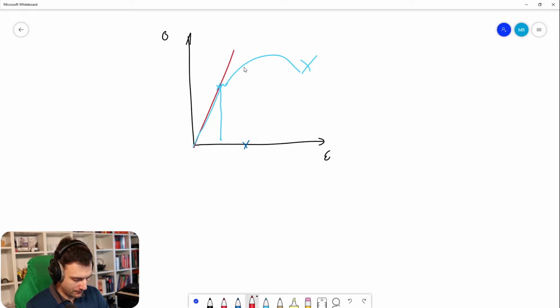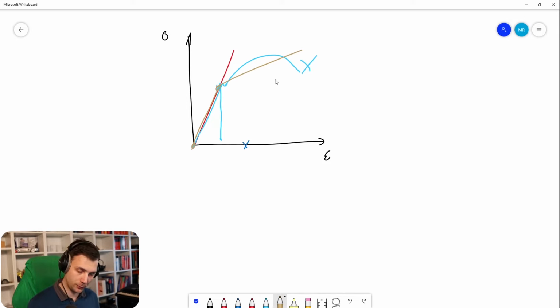Now, as we saw the differences, or when to include the nonlinear material model, the next thing we want to see here is how to model it. Because you don't have this curve modeled entirely. You could. There's quite a popular approach, piecewise linear: go along this curve and have different slopes and model it like this. This is one thing. And a subset of that, which is the easiest one and also the most used one, is the bilinear approach, where you just have two slopes. A linear one, which I just call E, and a slope on the plastic region, which I call ET.